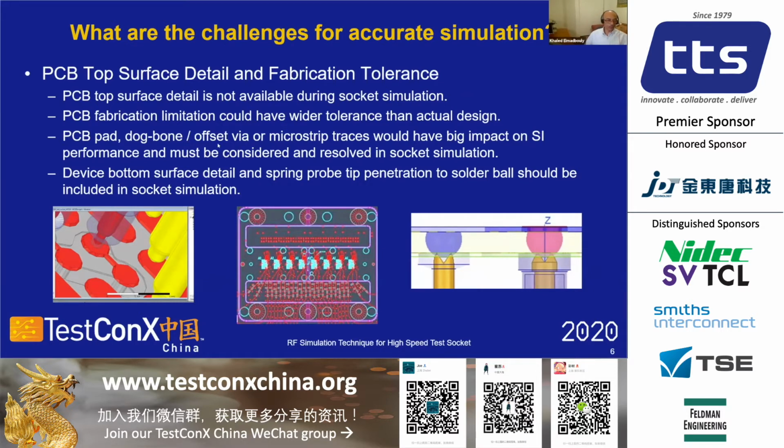The second challenge is the fabrication limitation. Sometimes the fabrication limitation has a wider tolerance range for the solder mask opening, the pad diameter, gold thickness, and all of that. Those can cause some degradation to the signal integrity performance, and we need to capture that.